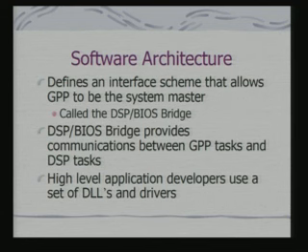So, the software architecture for OMAP defines an interface scheme that allows the general purpose processor to be the system manager, and this interface scheme is called DSP BIOS Bridge, and it provides communication between GPP tasks and DSP tasks.